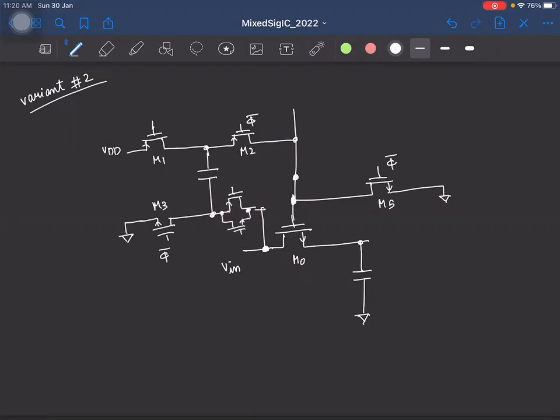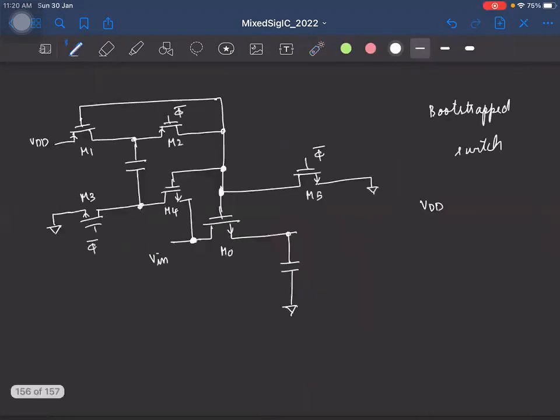So this needs to be clocked at phi. So the NMOS is clocked at phi and the PMOS is clocked by phi bar. Okay. And for this transistor M1, we saw that to turn this on, we can apply a voltage of 0 volt, right? But to turn it off, it was not enough if we connect the gate to VDD, right?